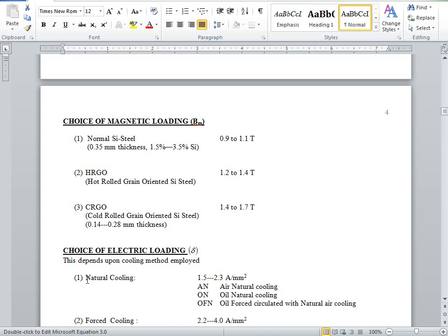It's huge. Reason, they are using better materials which can have the saturation of the knee point at approximately 2.4 Tesla even. Now since in the last 15-20 years the motors category or the materials have not changed that much, because there was no investment in this one. Now since electric cars are going to be the next future, you will see a little bit more advancement in materials.